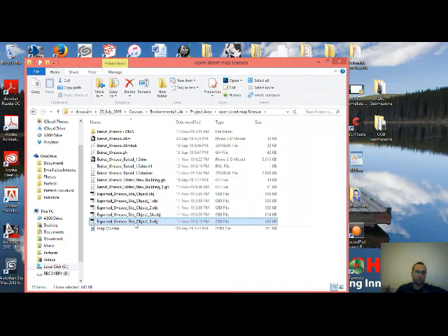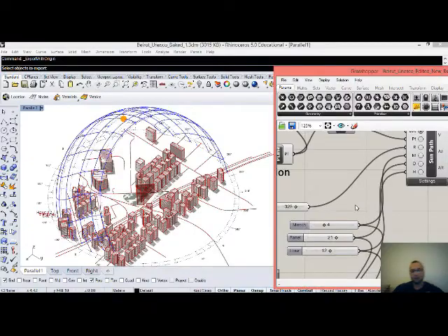Once you export your 3D model into the OBJ format, save it in a folder and give it an appropriate name. As you see, the OBJ format will have the .obj extension. The 3D SunPath available in the Grasshopper plugin of Rhino is as well available through the web-based tool.